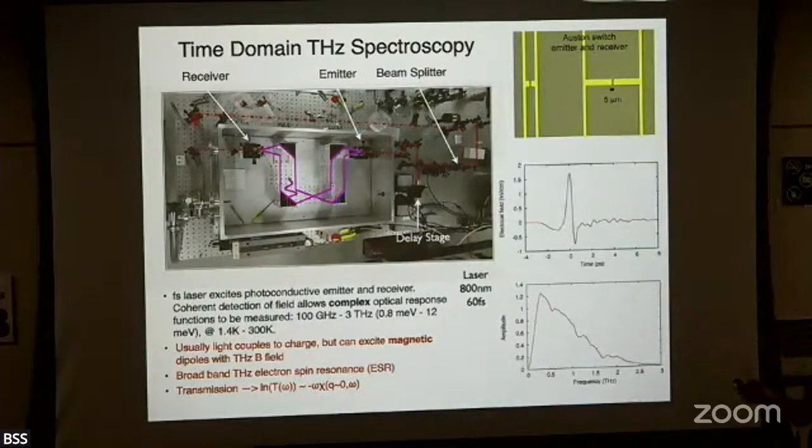Microscopically the current is coming at 80 megahertz, but you don't have detection electronics fast enough to see that. So you see a net boosting of current through the switch at some time. Then you advance the relative delay and hit it somewhere else. You get a larger average current in this fashion, and by sweeping out the relative delay, you can work this out.